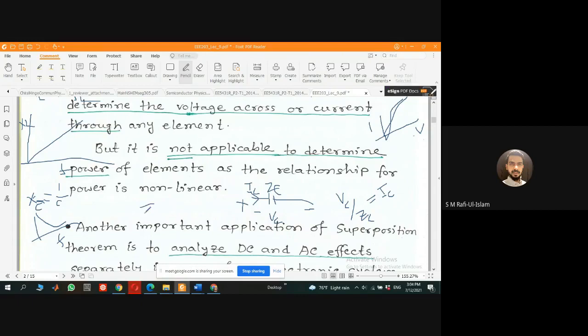If you have seen a capacitor in real life, it has two metal plates, and that doesn't change. If you buy a capacitor, it will always be, let's say, 5 microfarad. That 5 microfarad will never change. But if you connect that 5 microfarad capacitor to a different frequency, then that capacitor will show a different impedance.